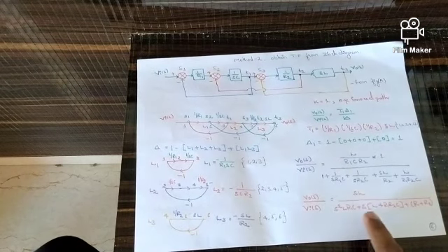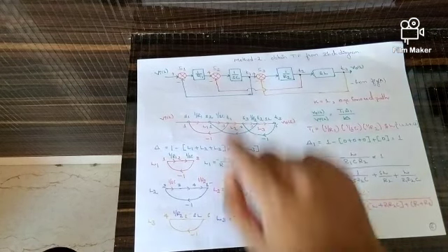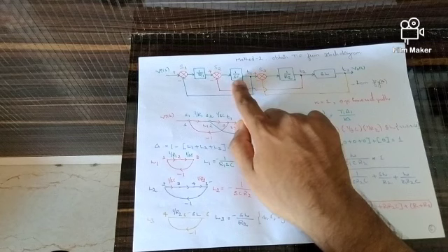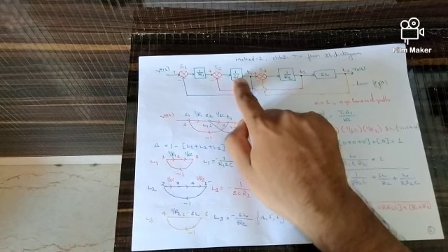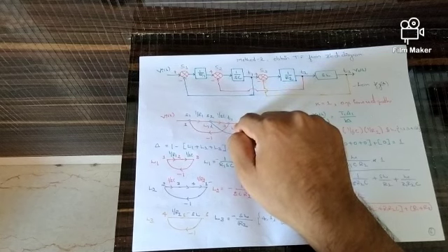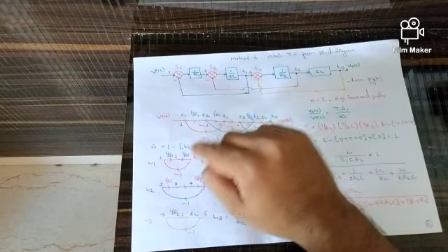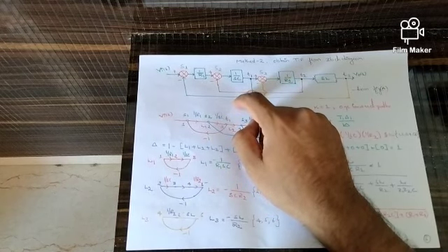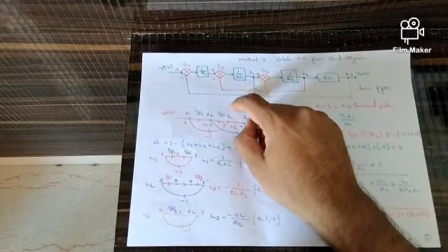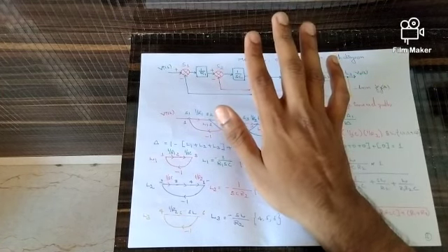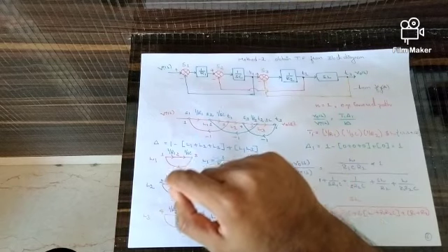One more important point that I need to add is, whenever you are doing block diagram reduction, you should not get square terms. Let's say I have G1 here, I have used some rules and I am getting a reduced block diagram, but I am getting the equation as G square. It is wrong. You should not get 2G1 or 3G1 or 4G1 or 5G1, something like that with a coefficient. Then you have done something wrong in the block diagram. These 2 points are very important.